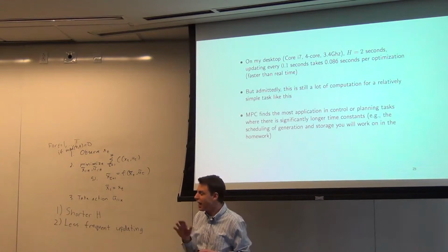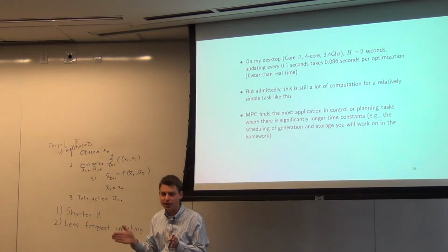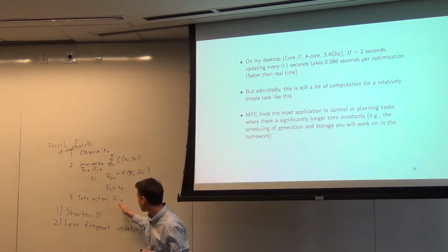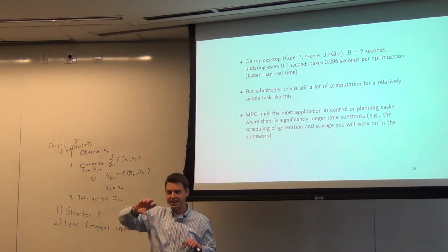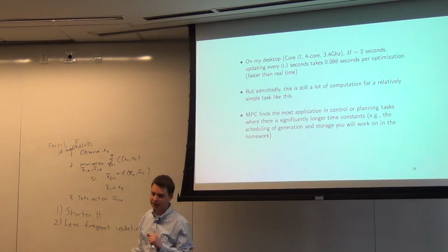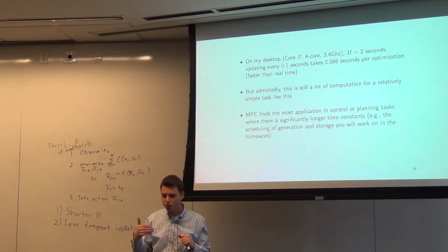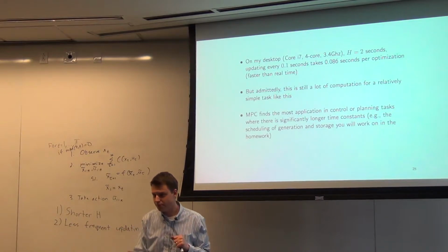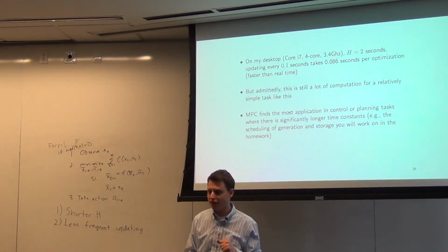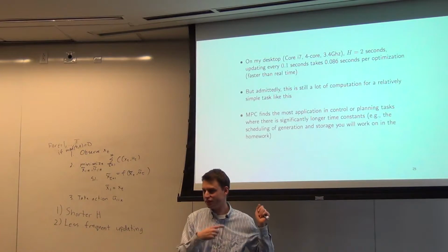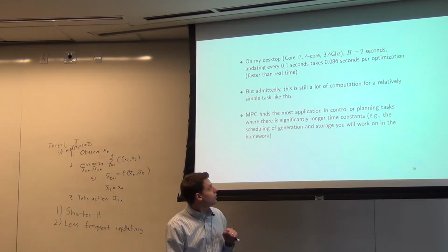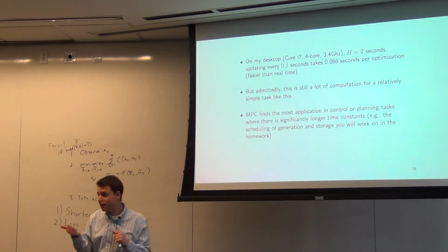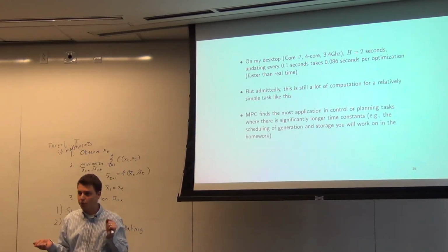Basically, by the time I solved it, and it's sort of weird because I've moved on a little bit, right? So I'm still taking these actions, but I've moved on a little bit from now. So maybe I don't quite take the first k, I take k+8 to k+8 or something like that. But still, I can keep up with the system in real time, as long as I can solve things faster, and it gives me new states. So that's good. We now have an MPC system that, even for a pretty high frequency control task like this, still looks reasonable.